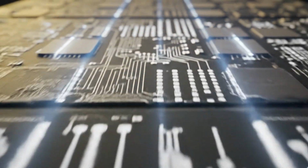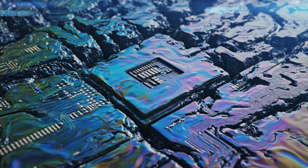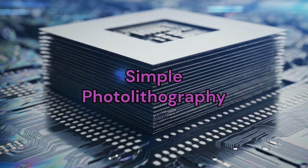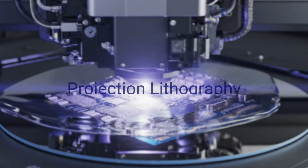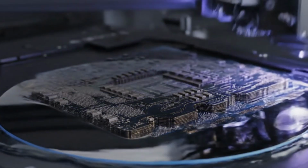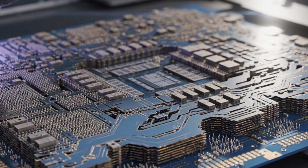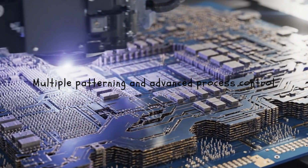If we briefly look at the history of semiconductor fabrication, the evolution is largely driven by how manufacturing techniques adapted to enable scaling. Early integrated circuits relied on simple photolithography with feature sizes in the micrometer range. Over time, advances like projection lithography, deep ultraviolet lithography, and immersion techniques enabled scaling into the nanometer regime. As traditional methods approached their physical limits, the industry introduced increasingly complex solutions like multiple patterning and advanced process controls.